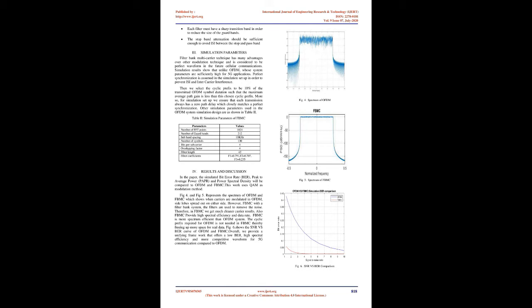Let us now observe the structural characteristics. On the transmitter side we use an array of N filters and filter banks, hence we can process N signals at a given time. The transmitter section uses an analysis filter bank and the receiver section uses a synthesis filter bank. Similar to OFDM, the input goes through S/P and is then passed through the analysis filter bank. Then the signal is again converted and the output observed is in serial form.